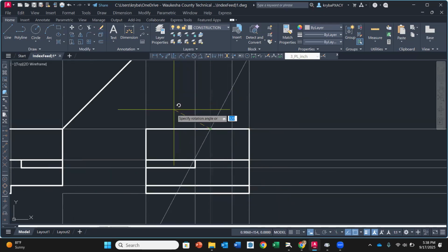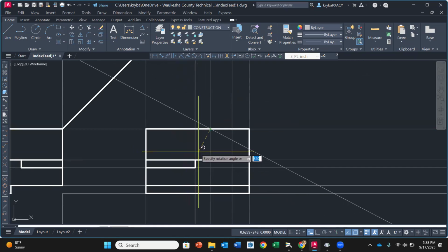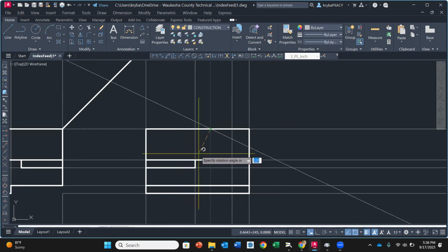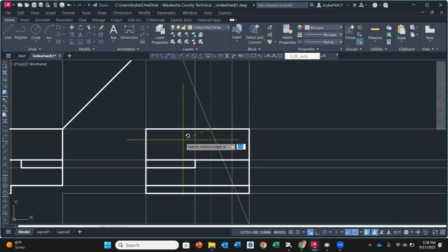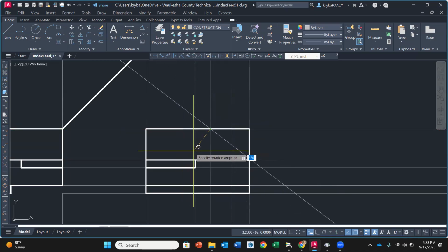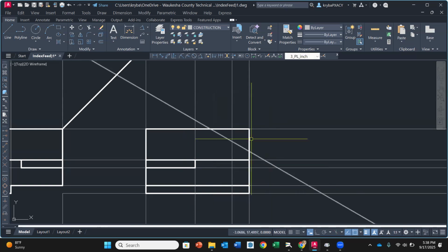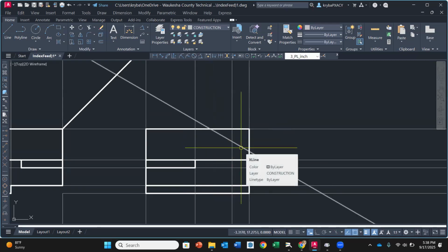And now what I needed to do is I needed to rotate. So from horizontal, this is 30 degrees. So from vertical, I have to rotate it in a positive 60-degree direction. Do you guys see that? Does that make sense? So I'm just going to put in 60. You don't have to put positive. So my rotation angle is 60. Okay. So that means then what I have left over here is going to be 30 degrees.